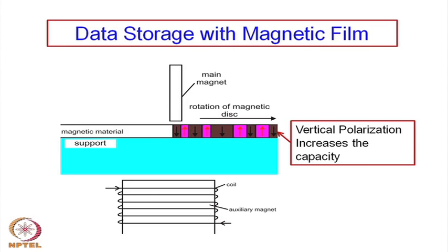That is the structure or the microcrystalline structure of those materials, the domain structure. You have to control the domain structure of the film. So, this becomes one domain and there is another domain, and they can be either vertically polarized. Okay. Of course, the domains must be controlled, the domain size must be controlled, domain directions, their anisotropic property must be controlled in such a way that they actually get polarized in the vertical direction. That is how we increase the overall efficiency.